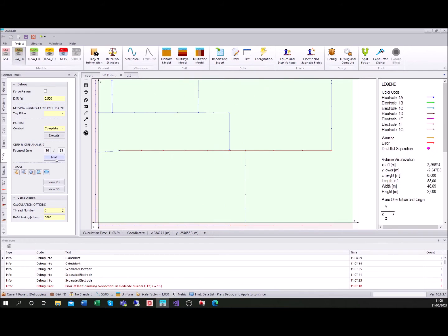Okay, we can extend, so we can see that now we have started to find the coincident errors. In these cases, consider that when you select the elements, you have a red highlight. When you pre-select the elements, you have an orange highlight. So you can see that if you make such a selection, there is a sort of short element just below the longer one. So we can delete this.